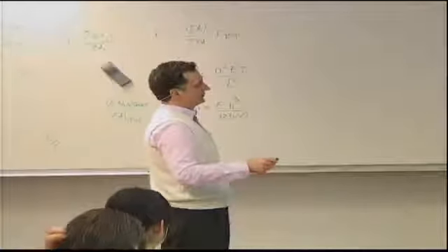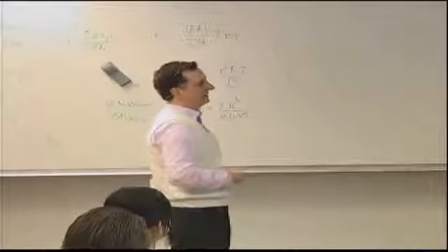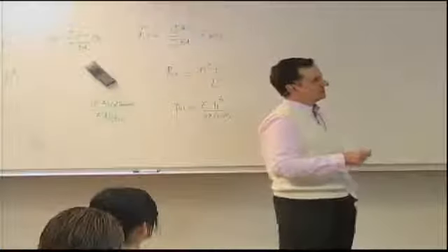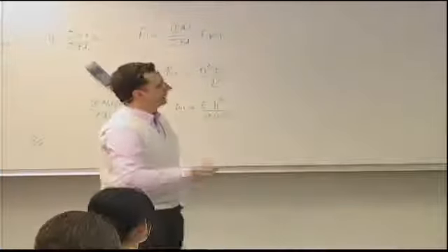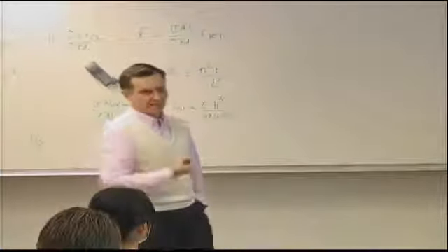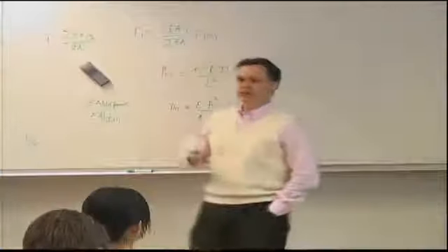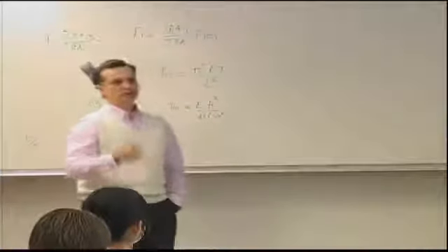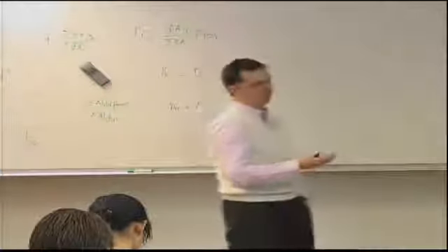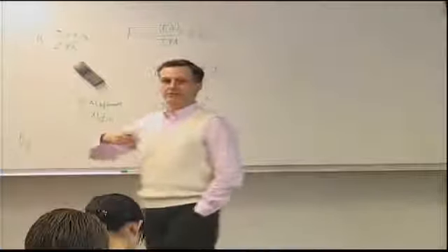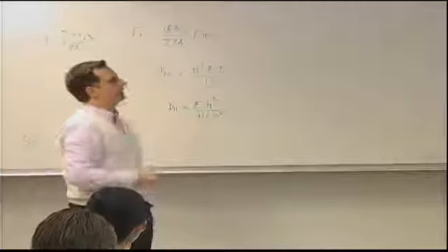One note to start talking about good designs: this layup has too many 0-degree plies stacked together. If you think about the mid plane, I have 4 plies above the mid plane and 4 plies below it, in order to maintain that stacking sequence. 8 zero plies next to each other is not a good idea when it comes to microcracking. When you cure and cool down, or when you have a mismatch of thermal expansion coefficients, that might locally lead to stresses that tend to put the matrix in tension, and you get microcracks.